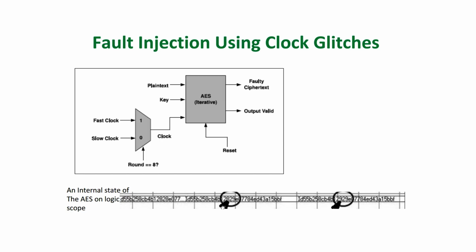So, this is the result when there is no fault. Now, if we inject a fault due to things like clock glitching, what we see is that this value of 282 gets modified to 292. What we observe here is that one bit has actually toggled. Instead of an 8, it has become a 9, indicating that the LSB bit of this particular nibble has been modified, and this modification has occurred due to the fault that has been induced.